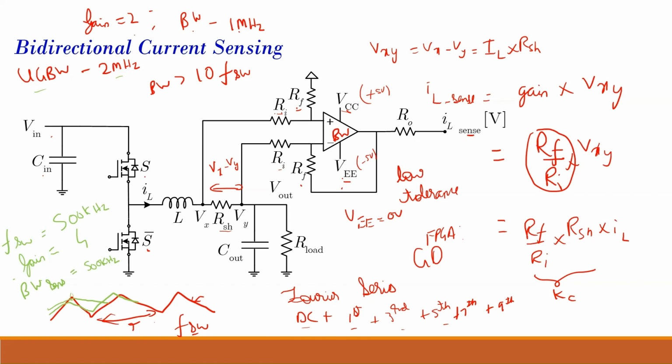If your sense signal should correspond to 2 volt but came out as 1.9 volt, your controller will compute based on 1.9 volt, which is erroneous, so its output will also be erroneous. That is why sensing is quite important, and you must spend sufficient time to get it right.